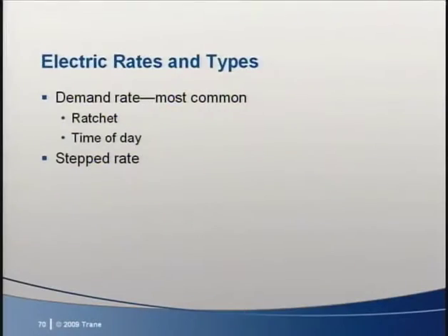Stepped rates can also be good for storage. They can be tricky to evaluate because we tend to look at them like a typical demand rate. Most times, the published demand charge in a stepped rate cannot be thought of or compared to a demand charge in a conventional rate. The actual, or as I call it, the effective demand charge, is not obvious.